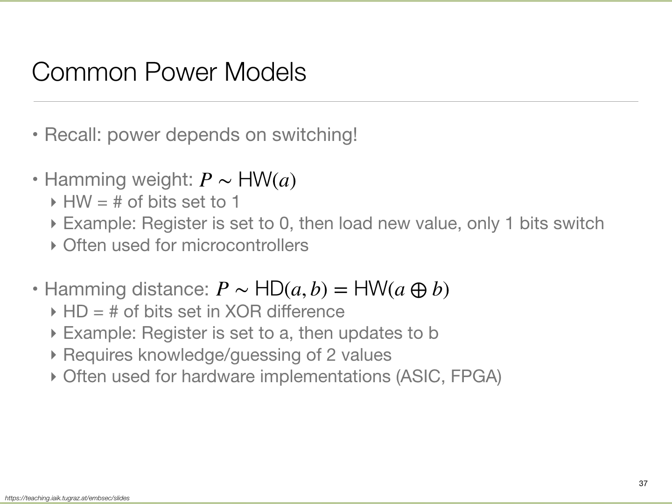These are called spread spectrum clocks, whose purpose is basically to flatten out the emissions. It helps a little with power, but even more so with the attacks I mentioned that use electromagnetic emissions, because by moving the clock around you are flattening out that side channel. So hardware can help, code can help, compilers can help, the OS can help. This is really a multi-layer problem.